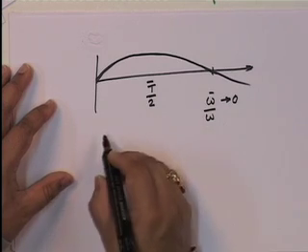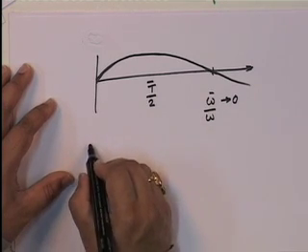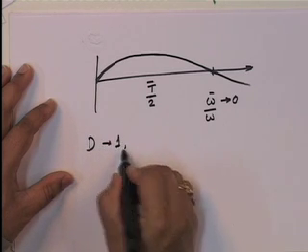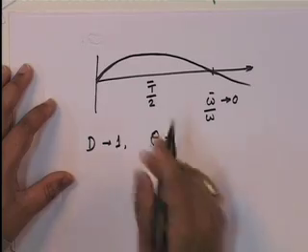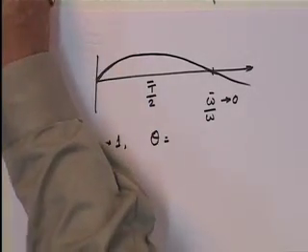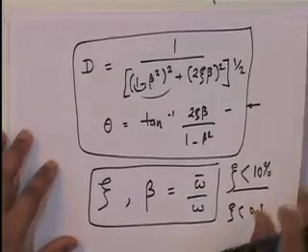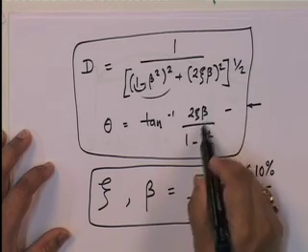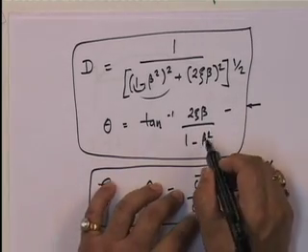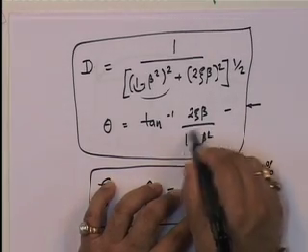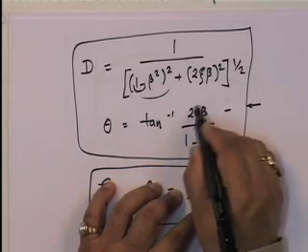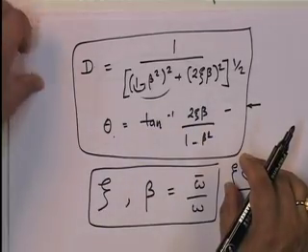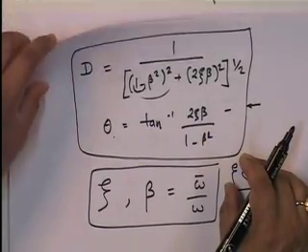let's substitute this in. So, let us see what dynamic amplification is: it tends to 1. And let us look at what happens to theta. It will be instructive to look at theta. Theta is tan inverse of 2 xi beta upon 1 minus beta squared. Now, beta is equal to 0. So, this becomes 1 and this becomes 0. Tan inverse of 0 is 0. So, theta is 0. That means what? There is no phase lag.